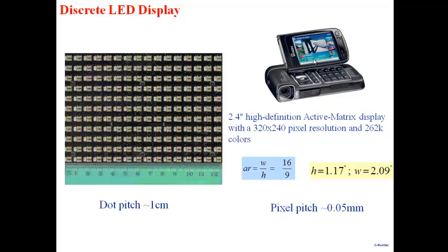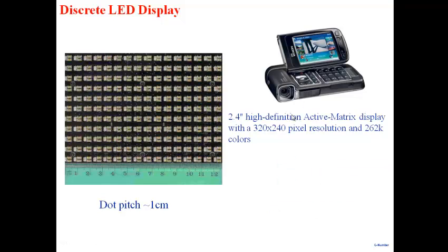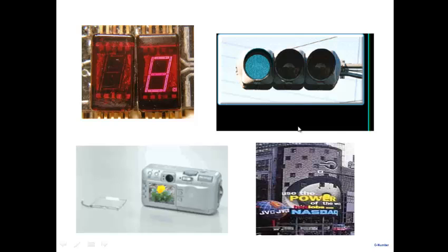And so now you see why we don't have displays made out of LEDs. The reason is I can't make those red, green, and blue LEDs on glass or on a cheap, common substrate. That's the first problem. If I go to a discrete way of making things, I can't achieve this kind of a pitch. So now you will appreciate why I can make these giant